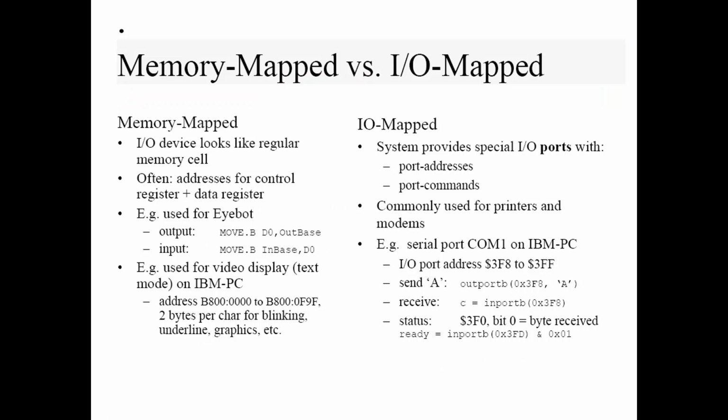As for the advantages, it simplifies the CPU design as the same instructions used for memory access can be used for input-output operations. That also allows for more flexible and powerful input-output operations. As per the disadvantages, it consumes part of the address space, reducing the amount of addressable memory. Example: accessing a display buffer or a network interface card, the NIC, through specific memory addresses.